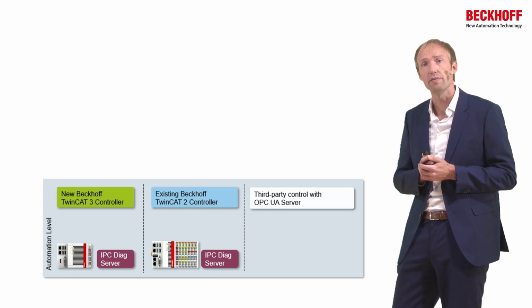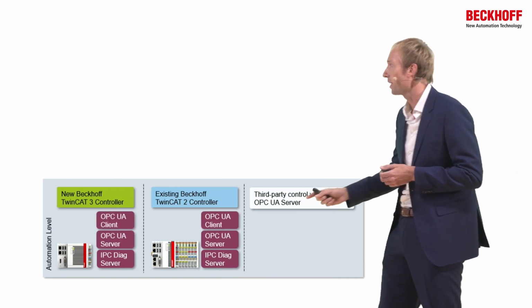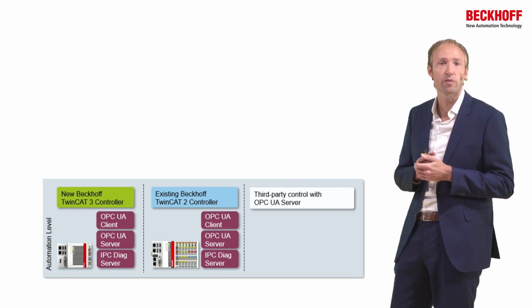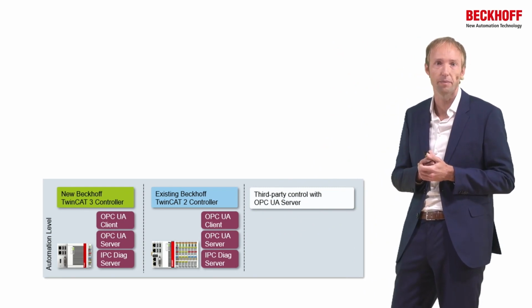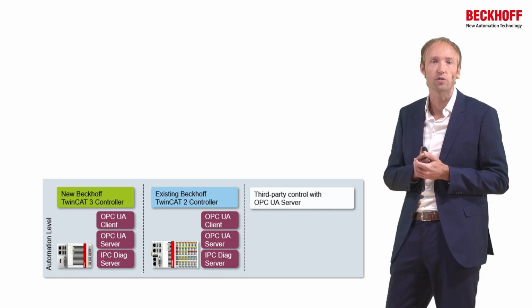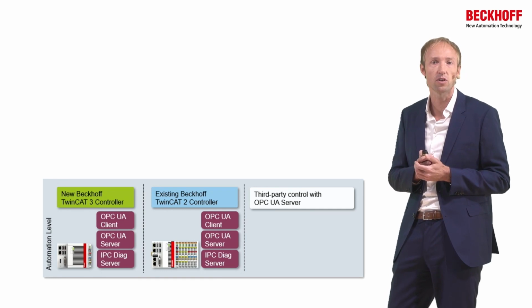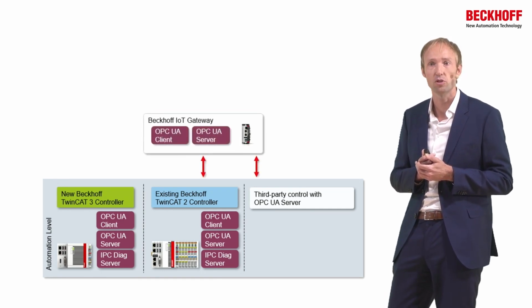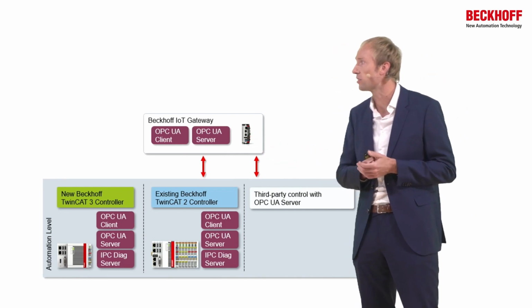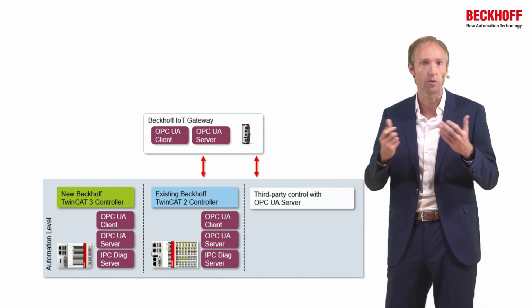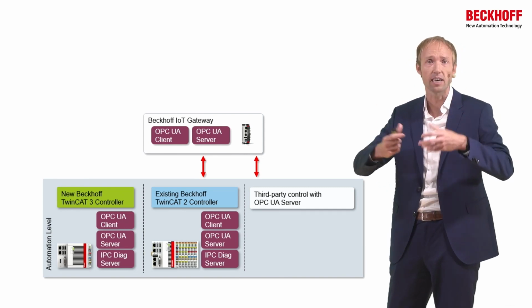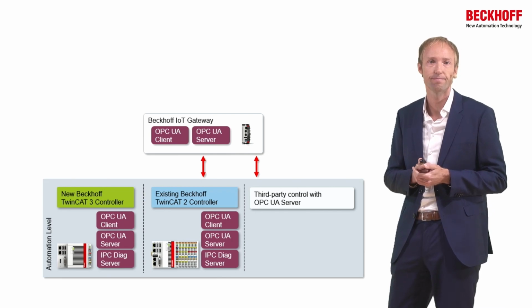In addition, we also have our TwinCAT OPC UA client and server applications running directly on the controller, and those applications offer access to or from the TwinCAT real-time. Because of the internal communication architecture of TwinCAT, these applications can also be installed and operated on an edge device, for example, to retrofit machines. So, for example, you can take one of our C6000 industrial PC series, install our OPC UA products on there, and then, of course, access other devices via the network.